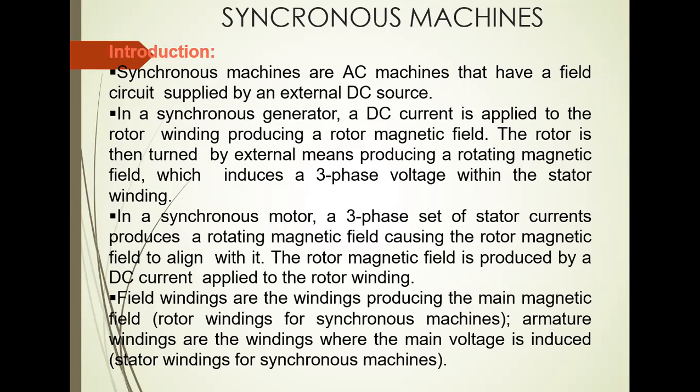So it has three-phase distributed windings on stator and DC excited field poles on rotor. So excitation system supplies DC current to field windings. Generally, the synchronous machine and the exciter for supplying DC to rotor field winding are mounted on the same shaft. The slip of a synchronous machine under steady state operating condition is always 0.